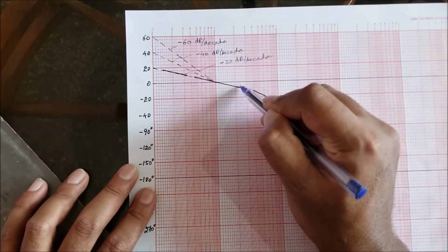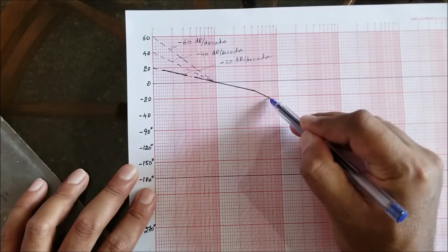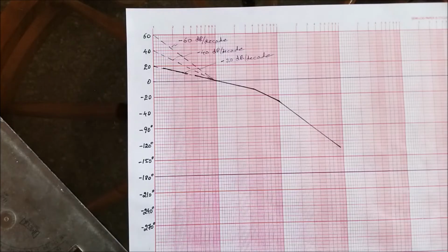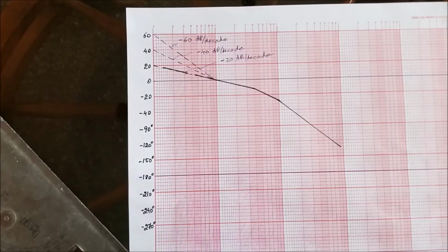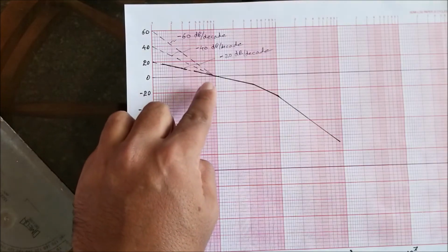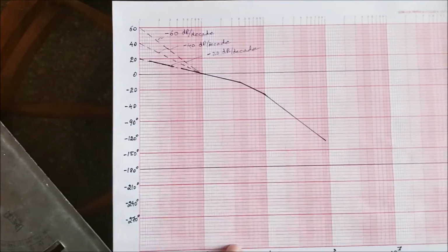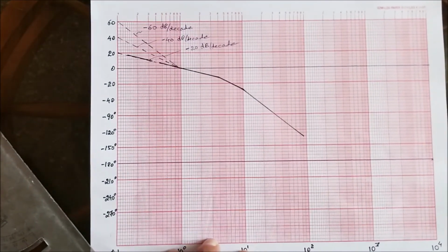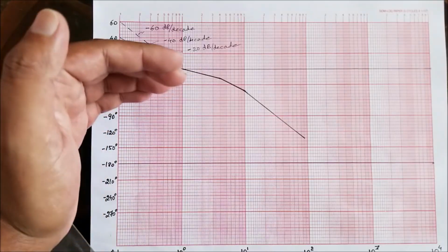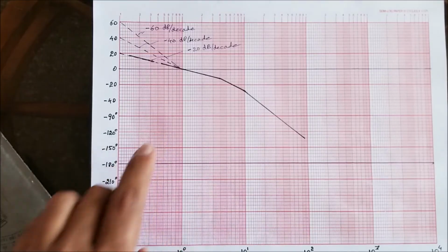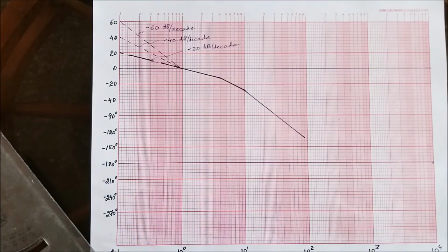So this is minus 20, this is minus 40, and this is minus 60 resultant slopes. The magnitude plot is over. Now if you ask me what is the gain crossover frequency, obviously it is 1 radian per second, because at 1 radian per second the magnitude plot is crossing the 0 decibel line. That itself is a reference to generate the slopes of various lines which is required, correct? If there is no shift, for all the problems, 1 radian per second will become the gain crossover frequency if we don't have any shifts, that is 20 log 10 k shift.